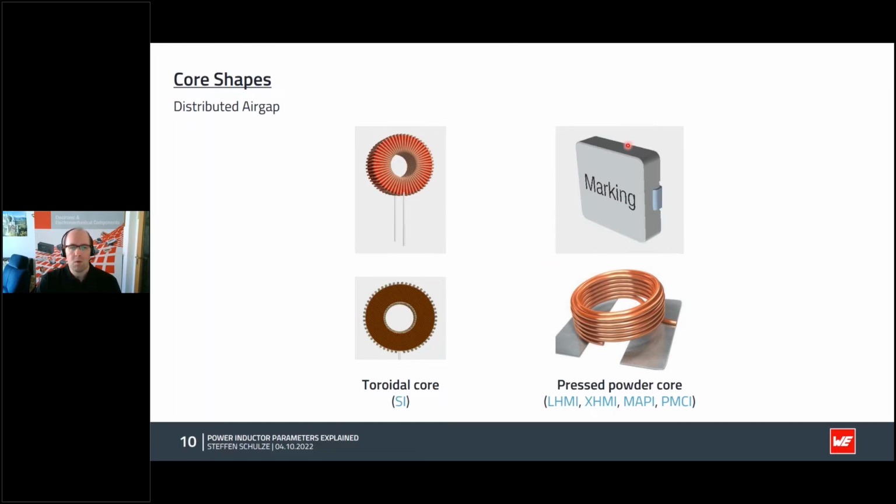So in order to create a compact inductor, those smaller materials based on iron alloys are created. For example, this version here, which you see, is completely shielded. So the internal winding is completely surrounded by ferrite material. In this case, the iron alloy material with a distributed air gap. So when it comes to shielding, those components are the best.